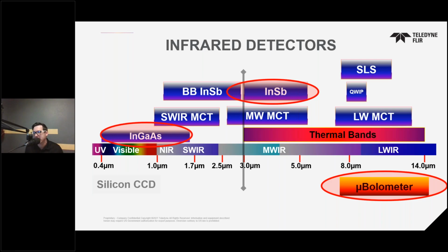Having an understanding of the most common detector types, such as microbolometers and cryo-cooled photon counters, is really going to help you move past the most important aspects of selecting an IR detector for your application. With respect to spectral filtering, a very obvious aspect is how the detector material's spectral response lines up with the exact target wavelength that you're trying to exploit or perhaps block. A very quick example: if you care about something that's happening at 8 micron, you can't really use an InSb midwave camera to address that. You're just not aligned spectrally at all. So, a very basic example there.